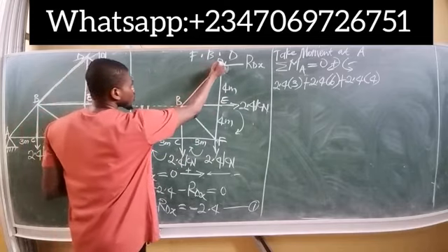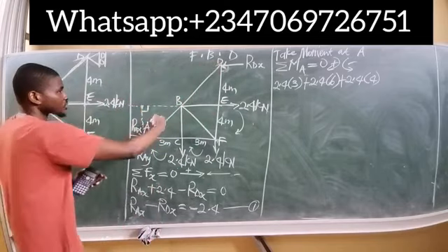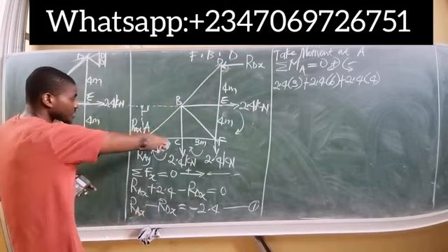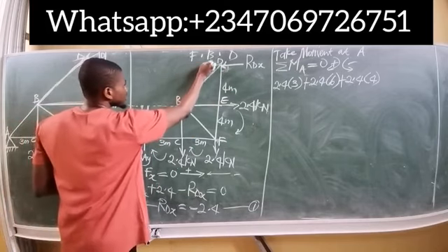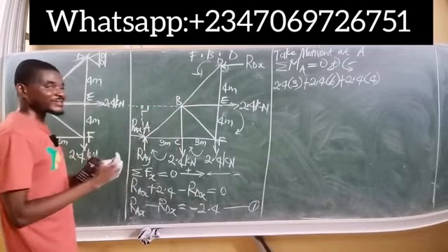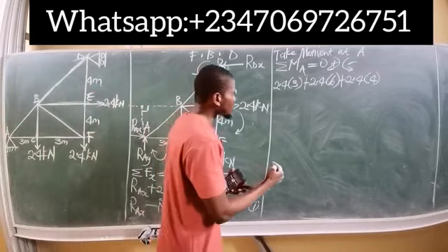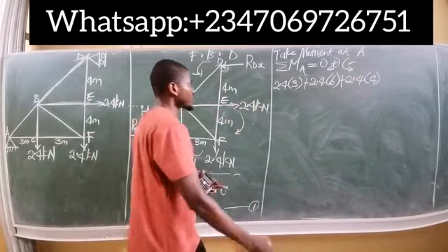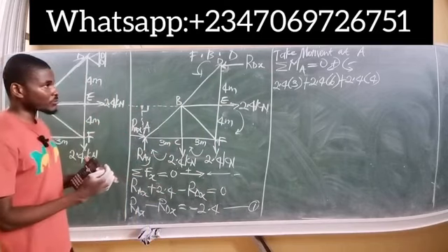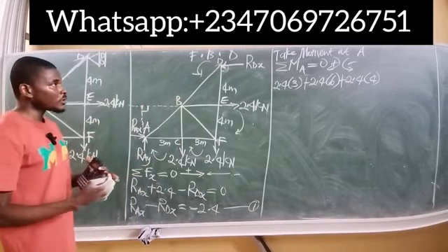Okay. Also, for the reaction at point D, this force is pointing to the left. So which means it will turn about this direction, which means its moment is simply in this direction. That's simply anti-clockwise. It is anti-clockwise to our direction. And anti-clockwise moment is simply what? We said, let anti-clockwise moment be negative. Okay.